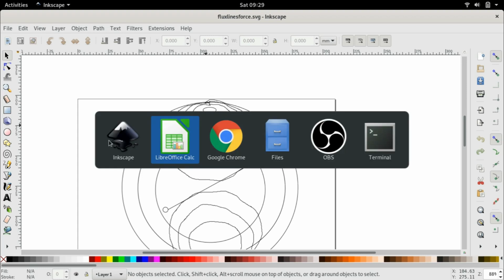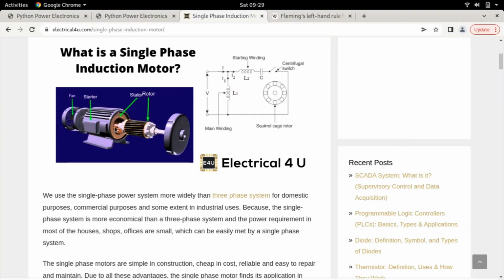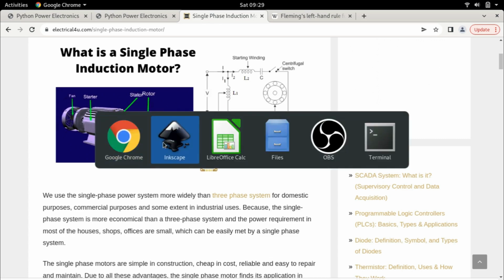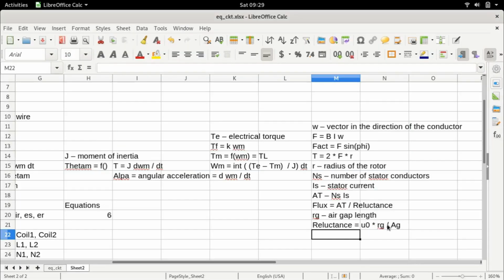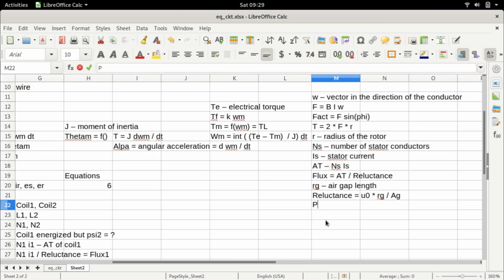Again, easier to say, let's go over to our diagram here. In this diagram, we can calculate the cross-sectional area as the area of this cylinder through which the flux passes. And this cross-sectional area will give us an indication of the area that contributes to the reluctance. So once we know the reluctance, we can calculate the flux. Once we calculate the flux, we can calculate the flux linkages with respect to the rotor. Here it is the number of rotor turns multiplied by the flux.